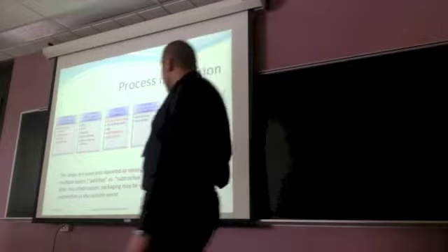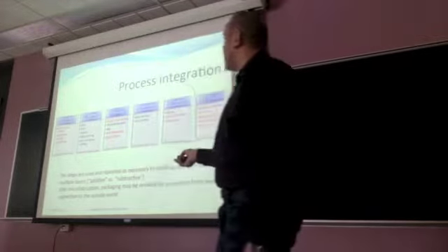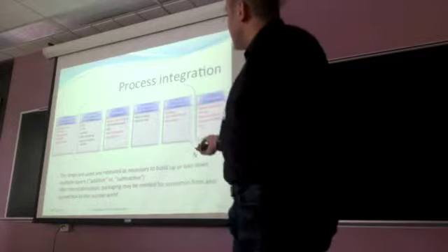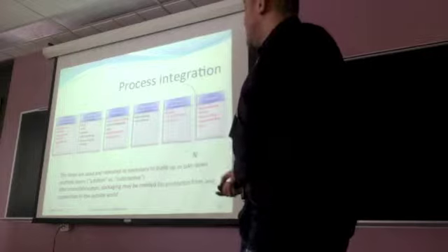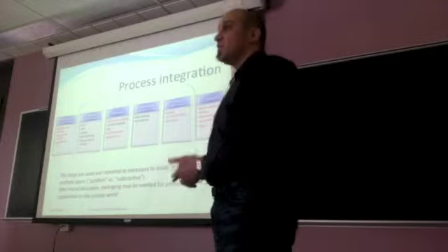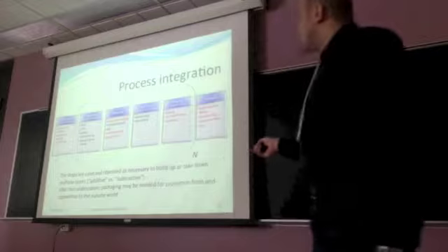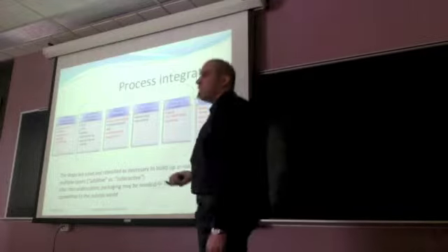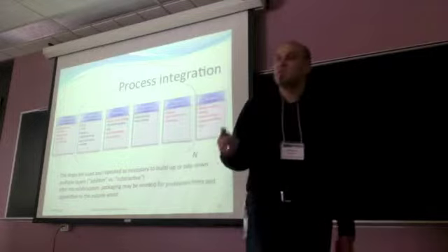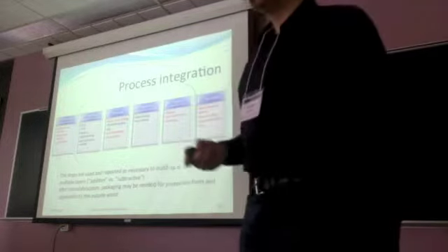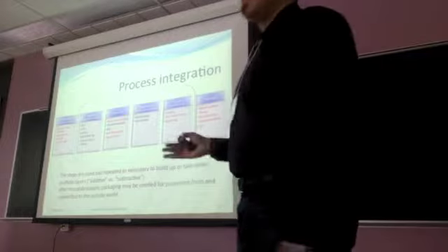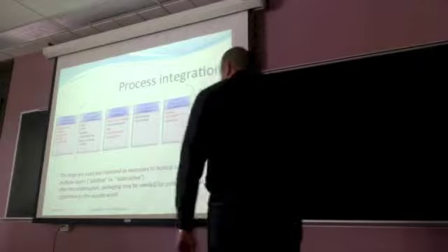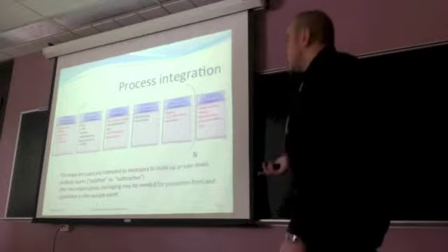David talked about soft lithography and nano imprint. We can remove material after patterning with etching, so wet and dry etching. We can modify the properties of the material. Doping and ion activation is widely used in fabrication of transistors to adjust the conductivity of contacts or channels. And these steps are used and repeated as necessary to fabricate your micro nanostructures.